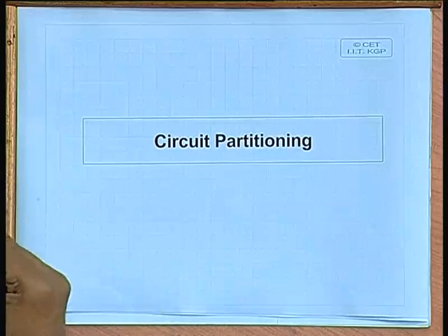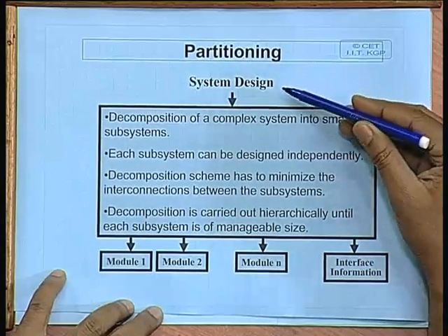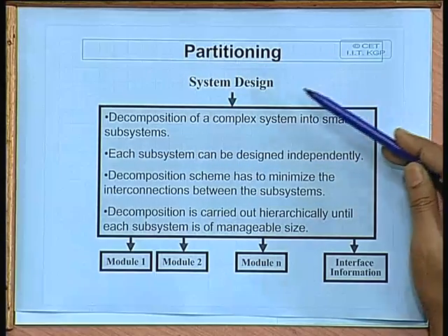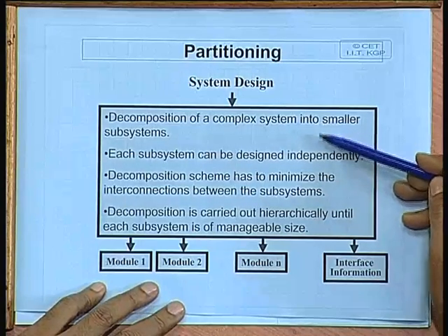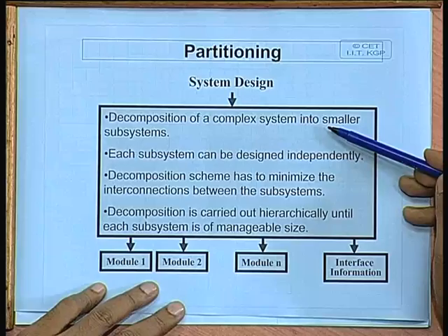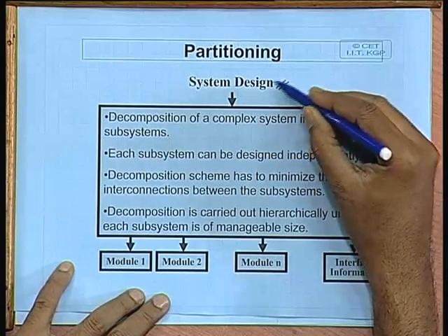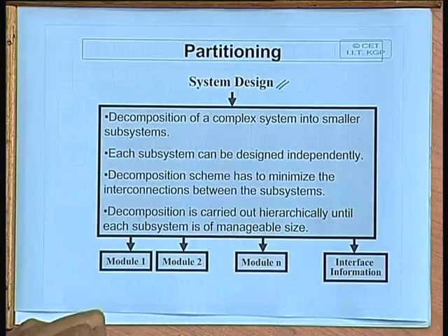target concept. So, first let us try to understand what the different goals of partitioning are, and what the partitioning problem involves. Broadly speaking, partitioning can be carried out at any level. Whatever I will be discussing today is applicable to system level partitioning, circuit level partitioning, even net level partitioning at a very low level, where the netlist may comprise transistors. So, we say that we have a system design, which can be a design at any level, as input, which is some kind of a netlist.